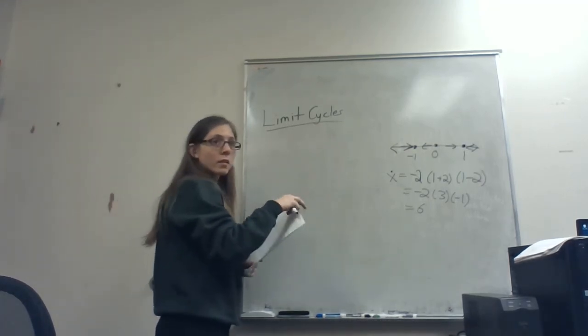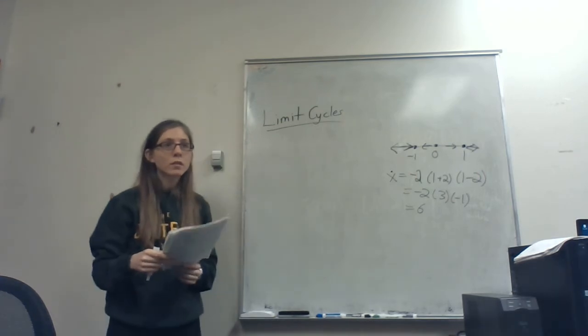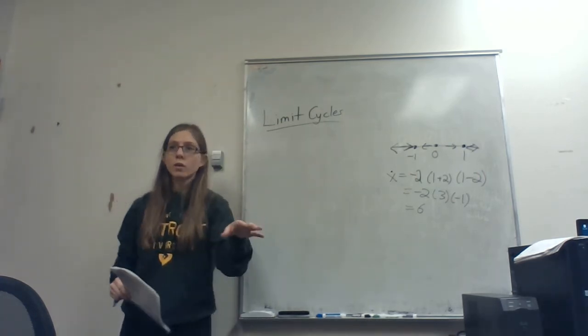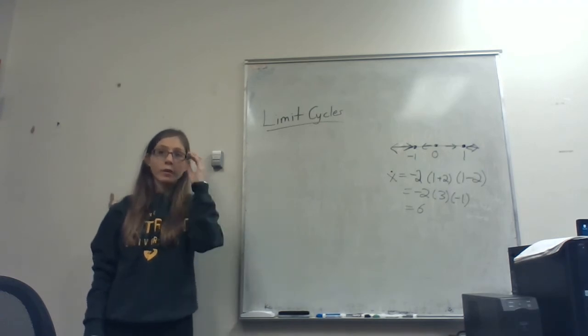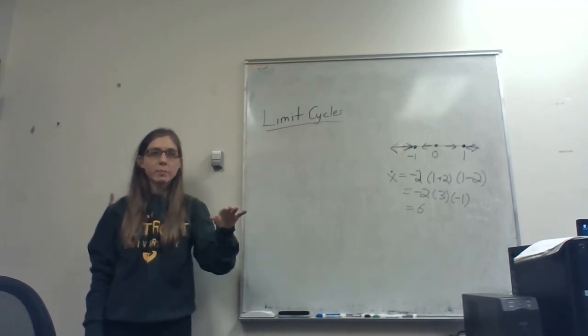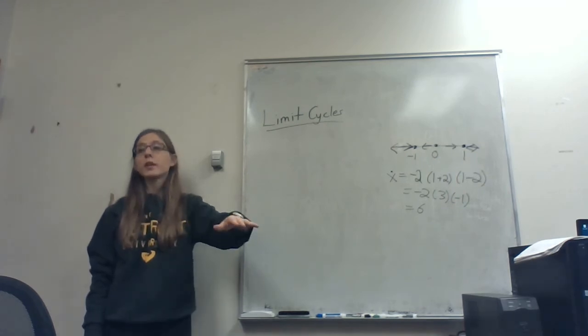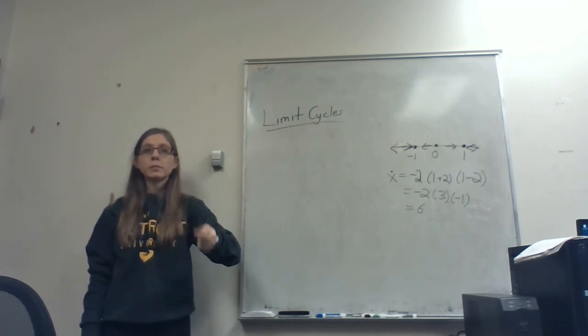But is a pendulum a stable or unstable system? Can we define this? No, because it has multiple equilibria. So that's what we have to be really rigorous about anytime we're talking about stability in a paper. We will never say stability of the system because it's completely undefined. But you can talk about stability of an equilibrium point.